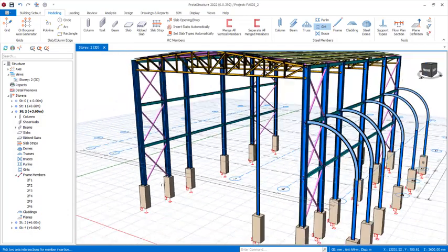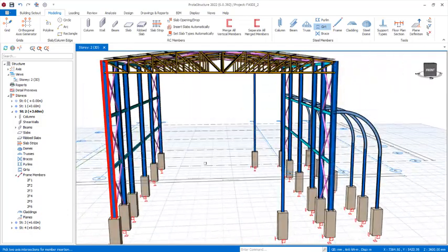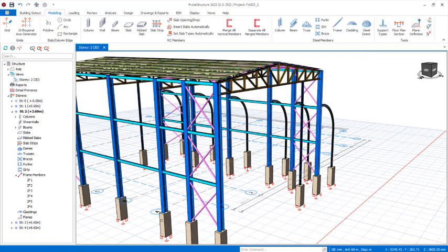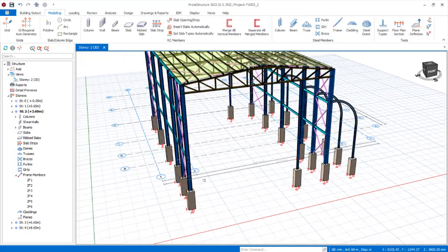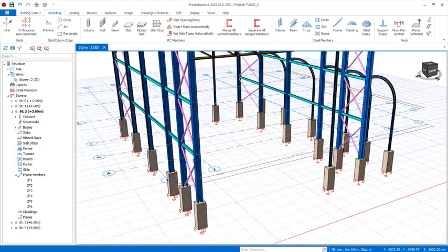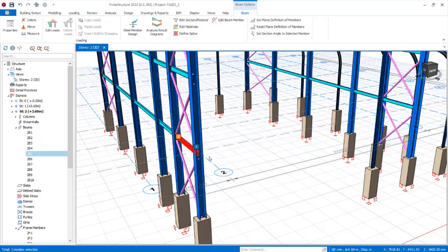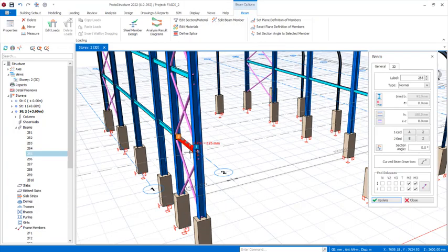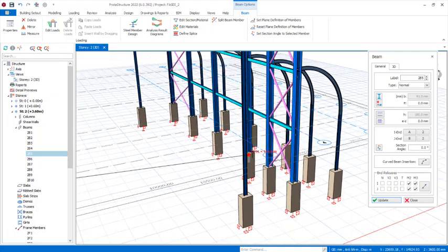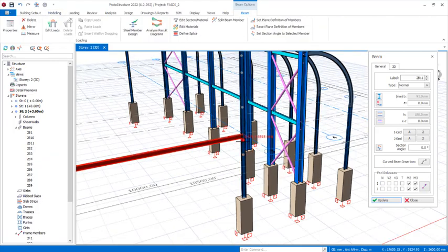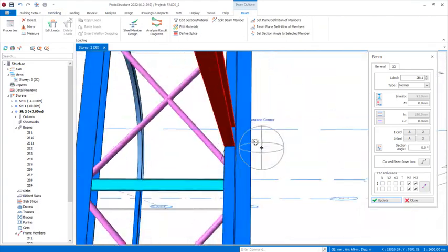But at first, I would like us to have a beam that will connect this column and this column. So for us to do that effectively, you just deselect the gates that you have already selected. At the level we are, this is level story 2. So you just select this one. We'll be using the property of this beam. Right click and then click on the property. You can immediately pick this first point, and then all the way to this point, you pick that to actually get the beam inserted just like this.